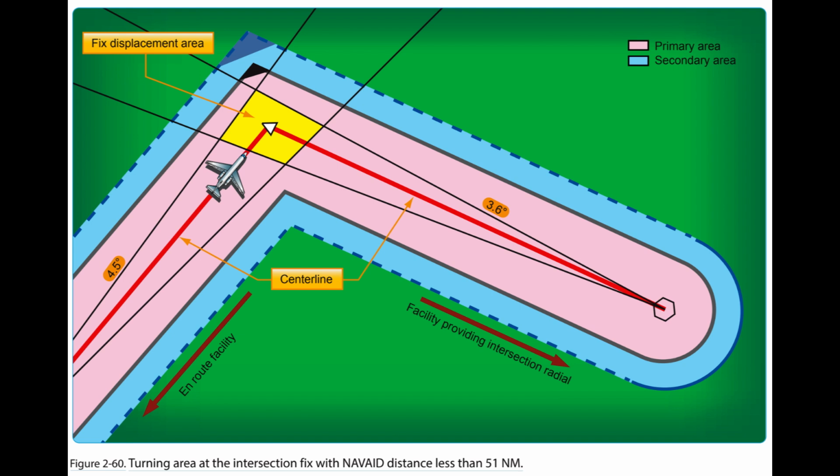ATC. Controllers have an important role in helping pilots remain clear of obstructions. Controllers are instructed to issue a safety alert if the aircraft is in a position that, in their judgment, places the pilot in unsafe proximity to terrain, obstructions, or other aircraft. Once pilots inform ATC of action being taken to resolve the situation, the controller may discontinue the issuance of further alerts. A typical terrain/obstruction alert may sound like this: aircraft call sign, low altitude alert. Check your altitude immediately. The MOCA in your area is 12,000.